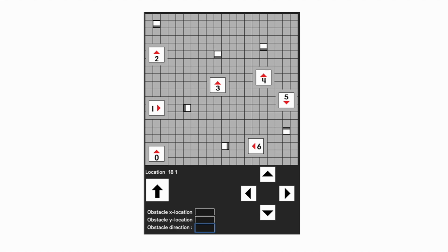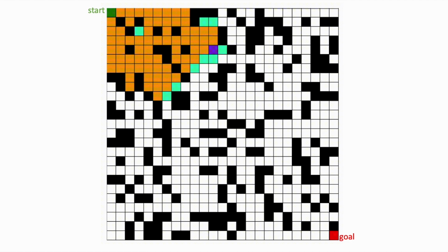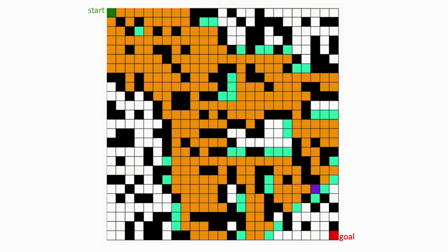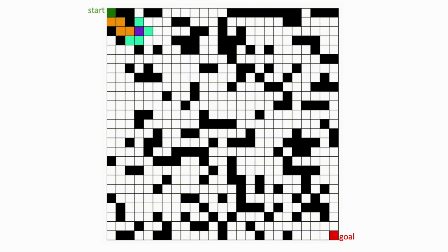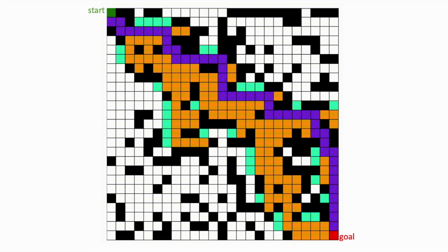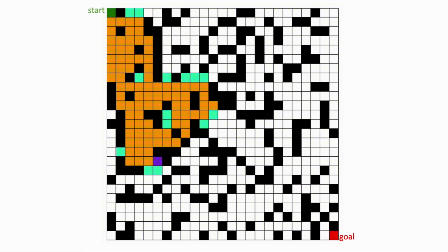This is done using a modified A-star algorithm, which adds all the neighbouring nodes of a current position into a priority queue and selects the node with the least cost to further expand upon. The cost of a node is the weighted sum of the cost of reaching that node from the start and the approximate cost of reaching the goal state from that node.